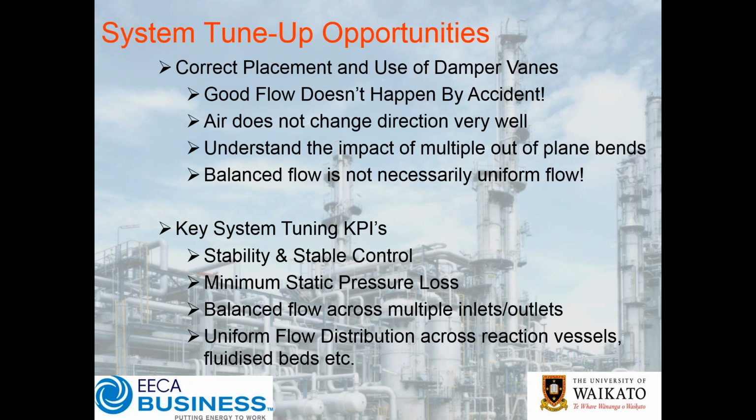So ultimately, what did we learn from this particular exercise and case study? Well, correct placement and use of damper vanes is very, very important. Good flow isn't going to happen by accident. The air does not change direction very well. We need to understand the impact of multiple out-of-plane bends. So that was the bends we were just talking about. And balance flow, so we got balance flow by taking out those damper vanes and using the VSD to control the airflow. However, what it didn't do was give us uniform flow across the actual bed itself, and so we had to take additional steps to realise the full potential of optimising the system.